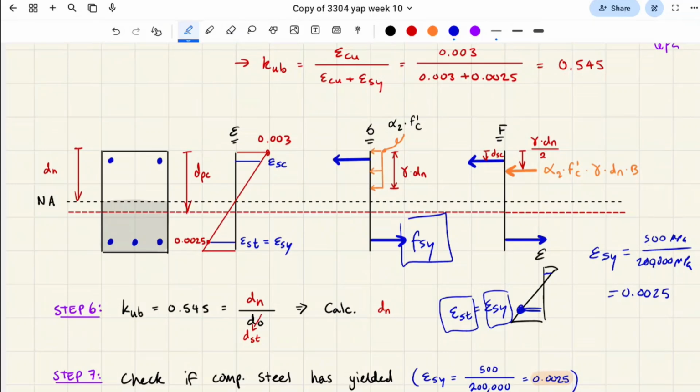So isn't it just when it's bigger than that? Yeah, bigger or equal to. But what do we know the number is? Basically, the definition of this whole point is that this is exactly when the steel yields. So it has to give you 500 MPa because we're exactly on the limit in this stage. Oh, okay, yeah. That's why.